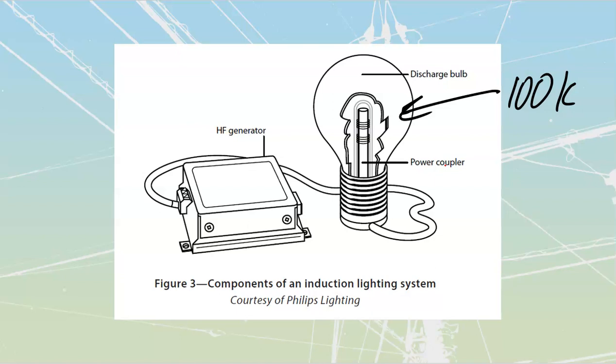They're fairly vibration resistant, low operating temperature, no stroboscopic effect, because the frequencies that they're going to be operating at are going to be in the tens, if not hundreds of thousands of hertz. No noise as well at the actual bulb. Sometimes the high-frequency generators can have a little bit of a buzz to them, but it's almost more of a whine, like that high-pitched noise you get out of a variable frequency drive.